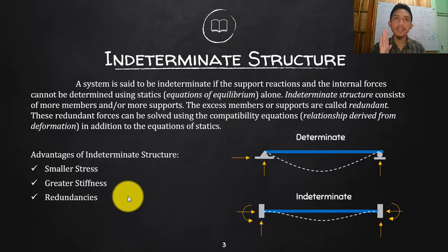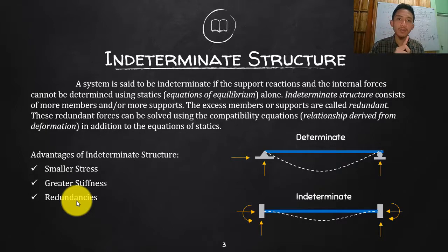By the sudden impact of that earthquake, there will be a sudden increase in the stresses on the members. And if the structure is just determinate, even if it is well designed, if it is not sufficient, it will break. But the good thing is, if there is redundancy, let's say there are a lot of members, that is what redundancy means in general. So there is an extra member that will carry the load even if the other member breaks. The structure will not collapse even if one of the members snaps.